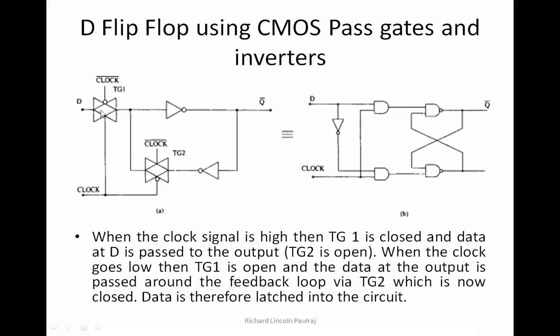So ultimately it will pass through NMOS, it will come here, then the complemented version. Then it will pass through the gate which is being enabled, and then finally I will get my output. So it is like a continuous loop here. You can find that it's a continuous loop, just that the data either passes through NMOS or passes through PMOS based on the clock, whichever is selected.